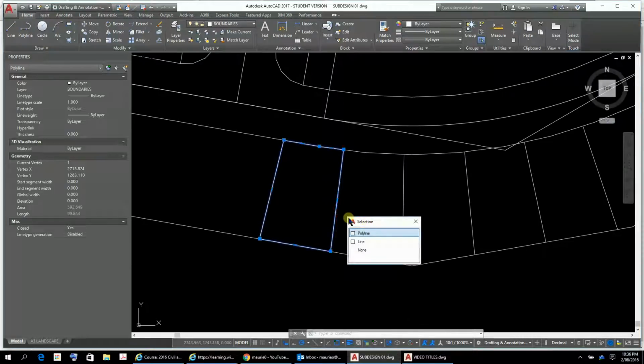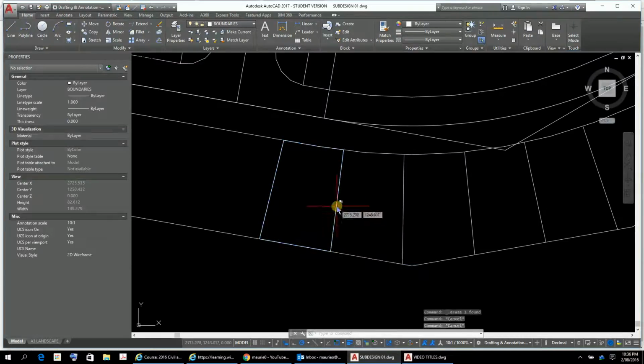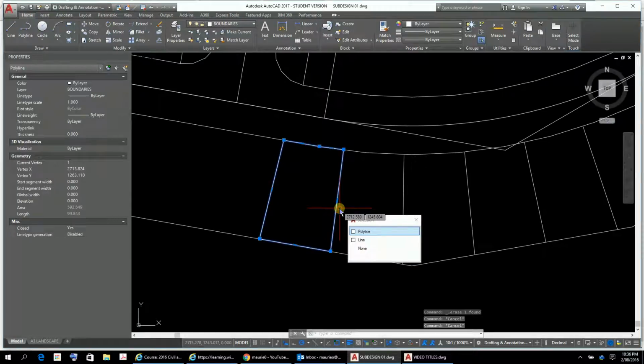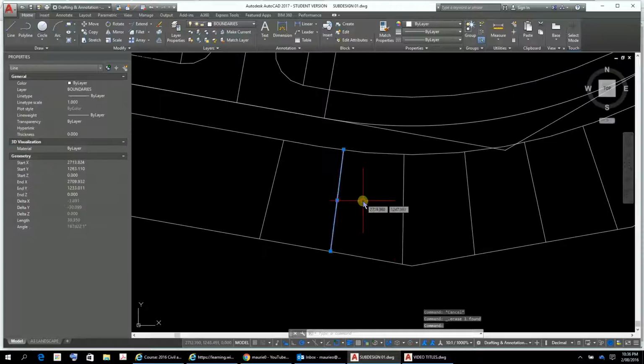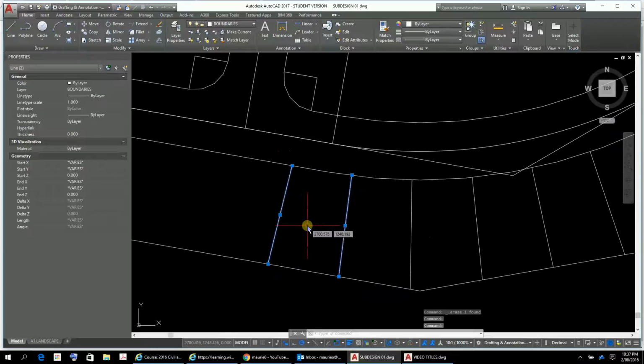Oh, I'm going to extend this one here. So yeah, I can delete the polyline. This is 592. Oh, I thought it was 590. 592, that's 8 over 30. It's roughly a third. So I'll go delete. I'll maybe go 0.3. Okay, so that's coming through.